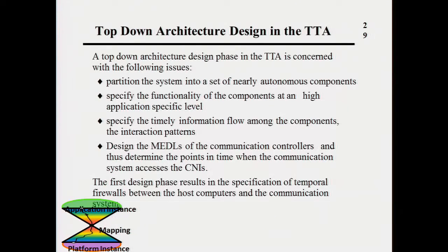You specify the timely information flow, so that when you need to have the information, the snapshot of reality and the reality itself are not too far apart. Then you design the message description list of the communication controllers and determine the point in time when you need to activate the communication. So the first design phase results in the specification of temporal firewalls, so of these boundaries of the TDMA slots.